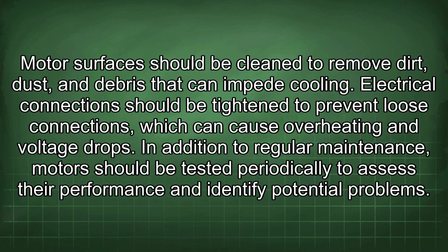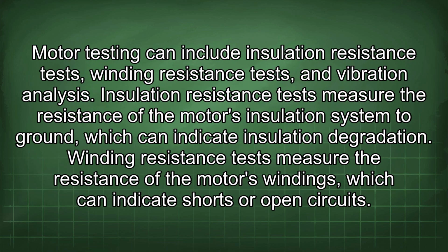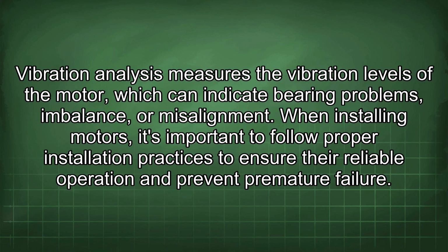In addition to regular maintenance, motors should be tested periodically to assess their performance and identify potential problems. Motor testing can include insulation resistance tests, winding resistance tests, and vibration analysis. Insulation resistance tests measure the resistance of the motor's insulation system to ground, which can indicate insulation degradation. Winding resistance tests measure the resistance of the motor's windings, which can indicate shorts or open circuits. Vibration analysis measures the vibration levels of the motor, which can indicate bearing problems, imbalance, or misalignment.